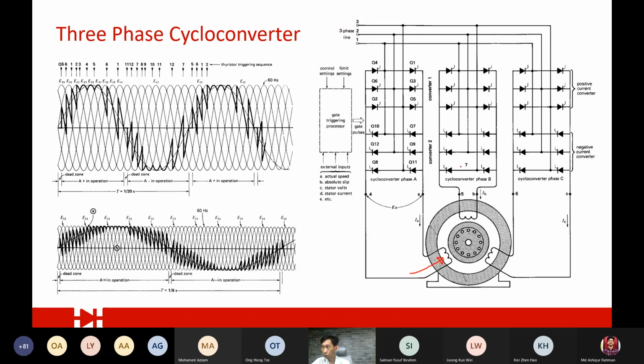So of course, if you have to control three sets, with the same frequency, you cannot put this one at 20 hertz and this one at 10 hertz. And if this one is 50 hertz, you're going to damage the motor, because it will cause a phenomenon called torque ripple. That means it does not rotate very smoothly. Because they have different frequencies, it will have torque ripple, jiggling.